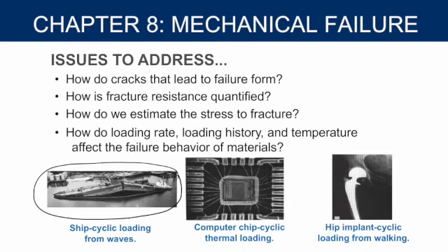What happened was the crystal structure actually shifted because of the change in temperature. The reduction caused the atoms to shift to a different crystal structure, and that structure was much less strong. And just the weight of the boat and the waves hitting the boat cyclically caused it to split in half. This is the same reason why the Titanic sunk back in 1912.